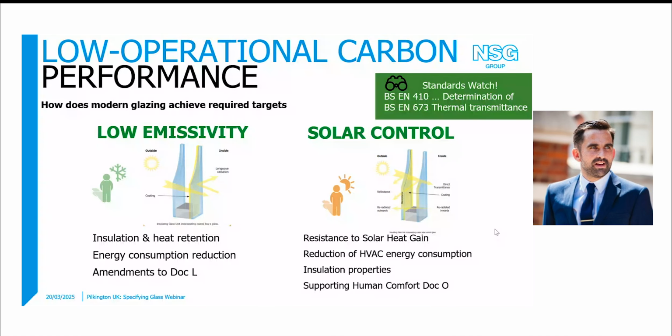The most frequently used glass technology within insulated glass units really is glass coating types. So in modern high performance IGUs, the two most frequently used, most popular would be low E coatings and also solar control coatings. So low E coatings' main function really is to reflect long wave radiation or heat back into the space. Will often be used in residential projects.